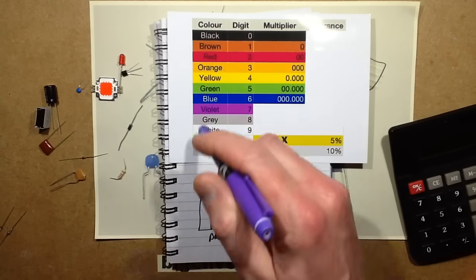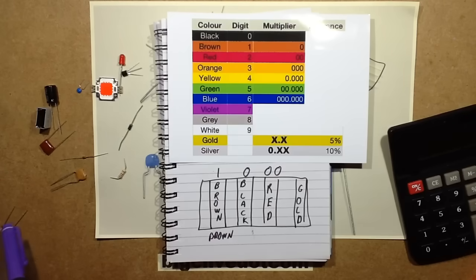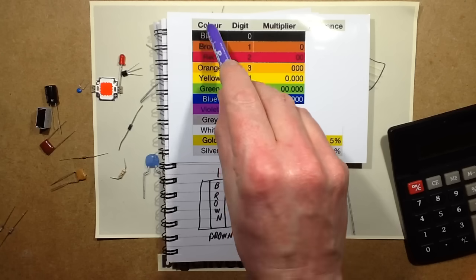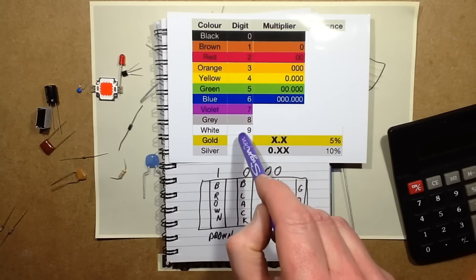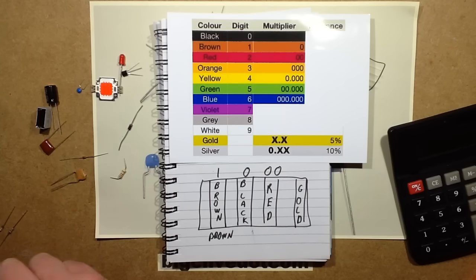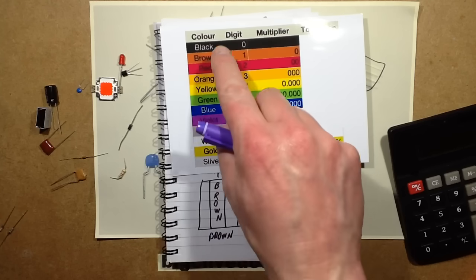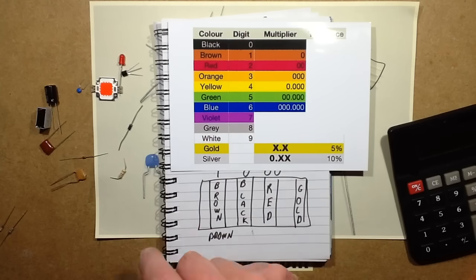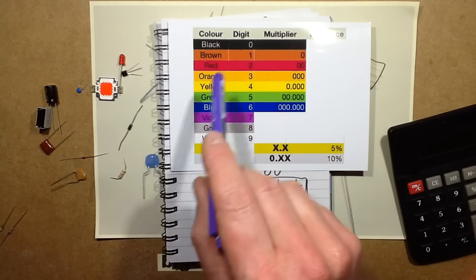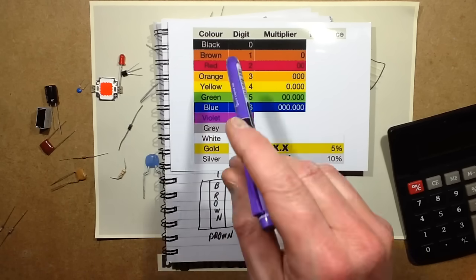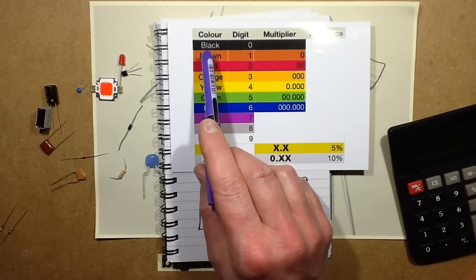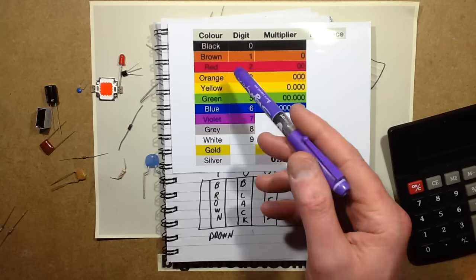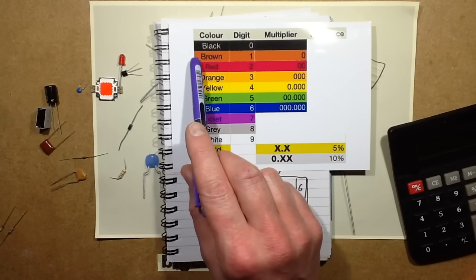So there are ways to remember this. The one I was taught with is Billy Brown revives on your gin but values good whiskey, and that's basically the colours in sequence, the first letter of the colours, starting at 0 and going up to 9. This is one of these things that seems a bit daunting when you have to remember a colour code like this, but the more you do it, the easier it gets. And there are really rude ones. It's helpful when the first word is actually the colour, because the first two letters are B, unfortunately. So Billy Brown, the brown indicated the brown colour.